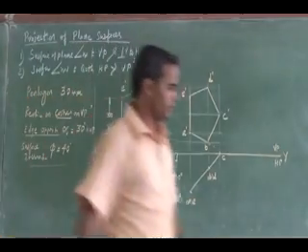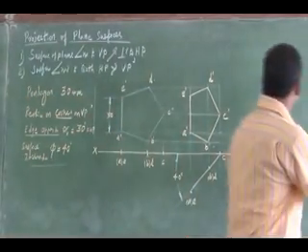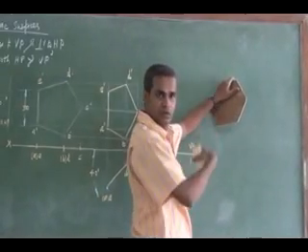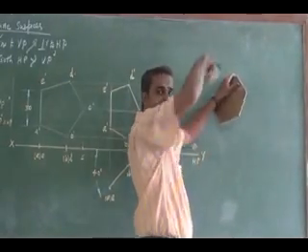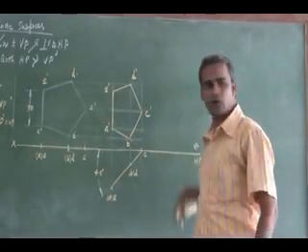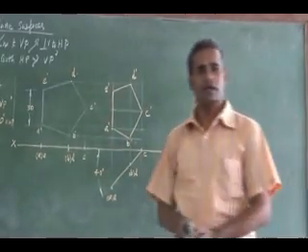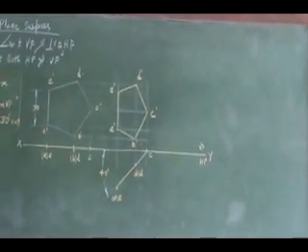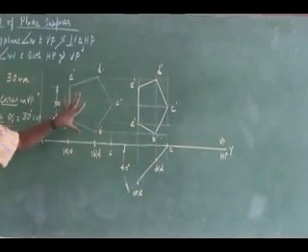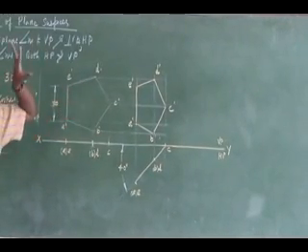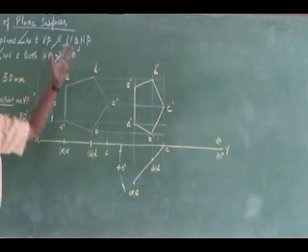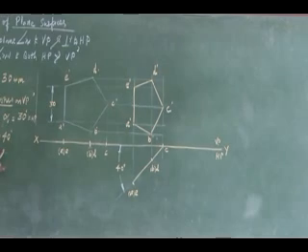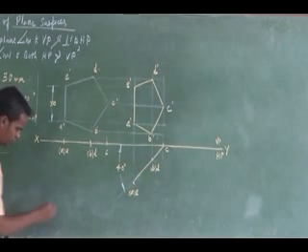So if the plane is inclined like this, I can see a front view for this, and I can see a top view for this. Some other shape I will have. That shape, front view and top view, you have to get. So the very first step, how you have to proceed, is to draw the true shape where the surface is inclined. In which plane is the surface inclined? It is 40 degrees.